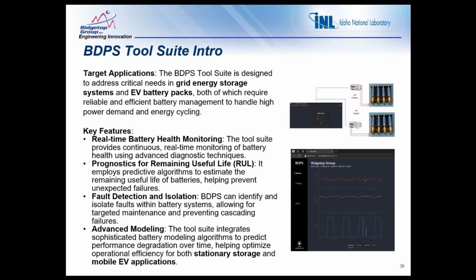life testing capabilities, and then keeping track of that data to have a model feedback and making informed decisions for second life applications. So with this, we'll be introducing some capabilities for real-time battery health monitoring and diagnostics, as well as the prognostic element when processing model data versus a BMS acquired data stream, and comparing that with ARULE to do things like fault detection and isolation.